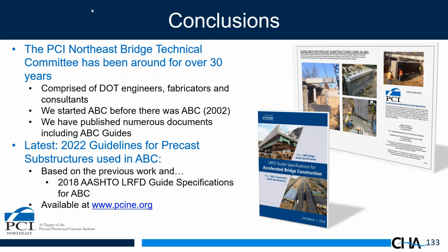There's a question that came in beforehand on what are the precast bridge unit life cycle expectations, and how does this compare to cast in place, maybe a concrete deck with potentially less porosity? Yeah, the question was with respect to PBUs, which we refer to as prefabricated bridge units, which are two beams with a precast deck on top, essentially making a double T. They're also in AASHTO referred to as modular deck beams. So there's two names out there.